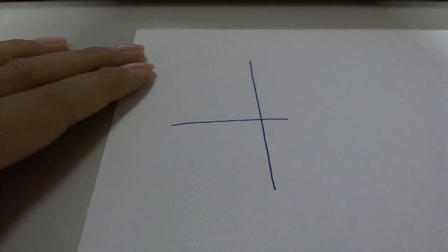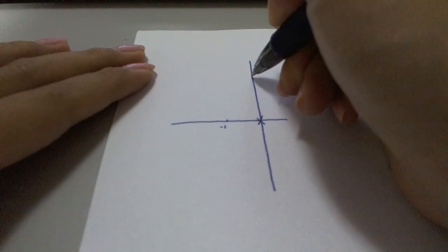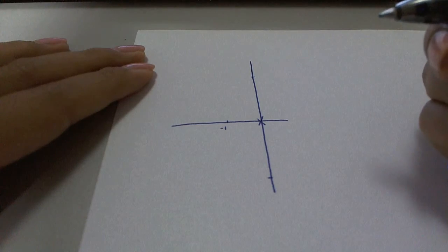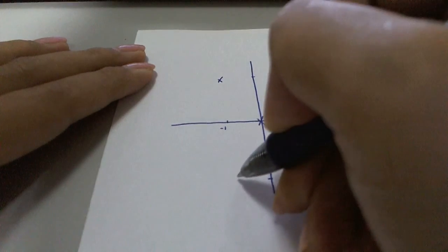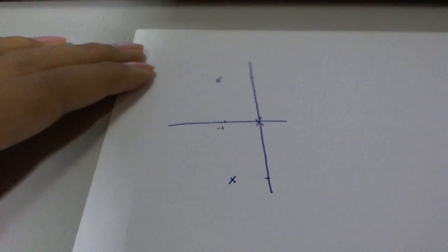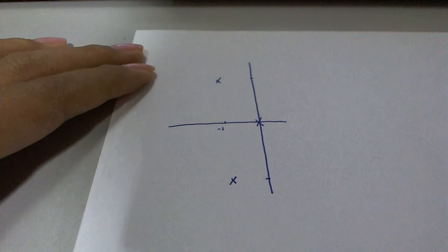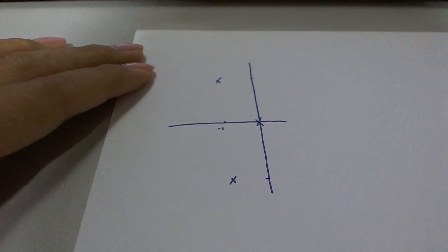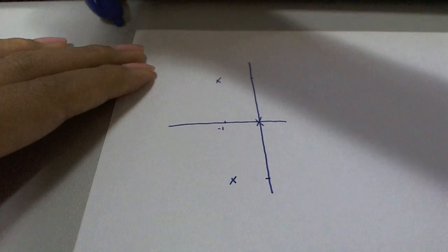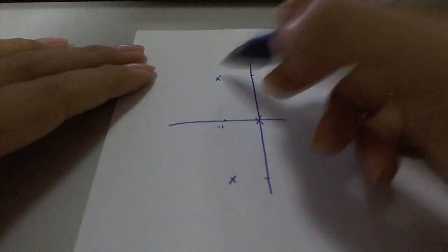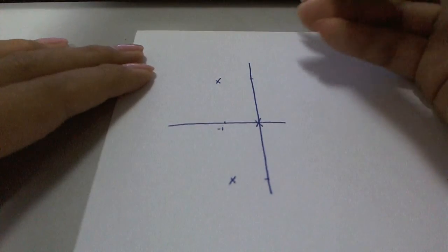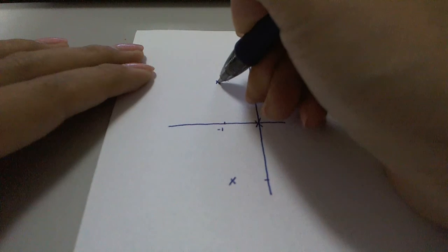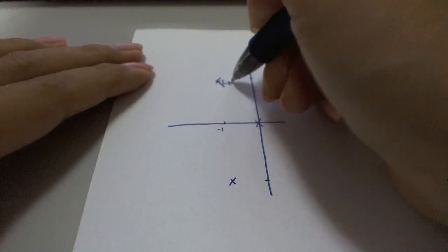The starting points are at 0 and also -1 plus minus 2.2361. So those are our 3 starting points of the root locus. And next we find the angle of departure. First is minus 24.1 from this pole over here. So it will go down at minus 24.1.